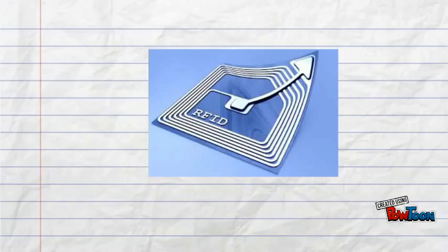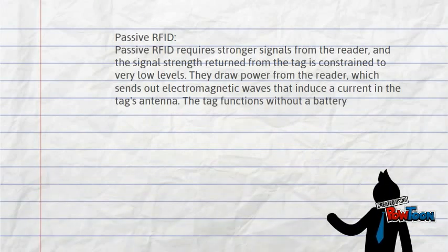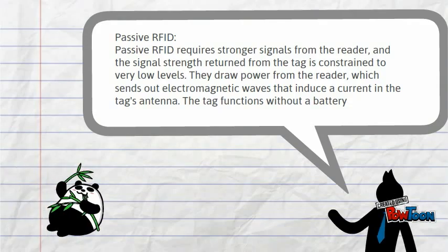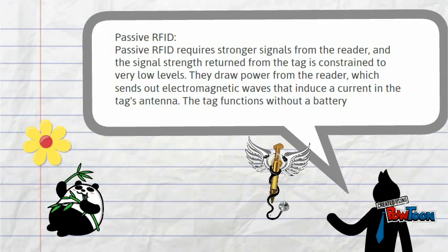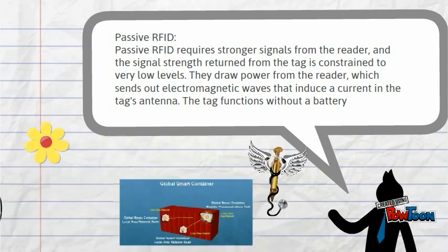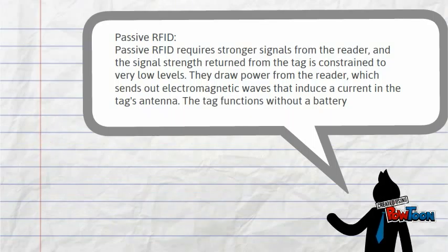The long-term maintenance cost for an active RFID tag is greater than that of a passive tag if the batteries are replaced. Battery outages in an active tag can result in expensive misreads. Active tags can be used for tracking containers, medical assets, or monitoring environmental conditions in data centers.